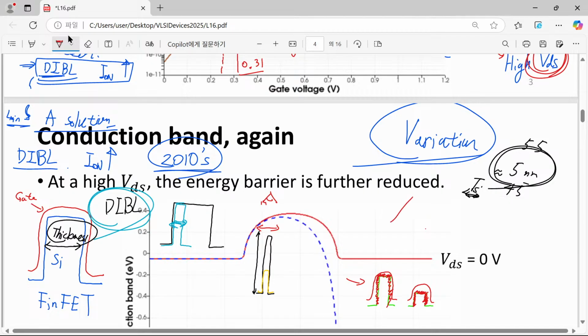From the viewpoint of a top view, let's say that this is a wafer top surface and this is a wafer bottom surface, and now we are using the same length scale, but inside it we have a much wider device. It's like just a magic word trick, but it really happens in our case. The only difficulty related with this tall fin is that it is difficult to fabricate. So as much as you can fabricate it, you will love this tall fin.